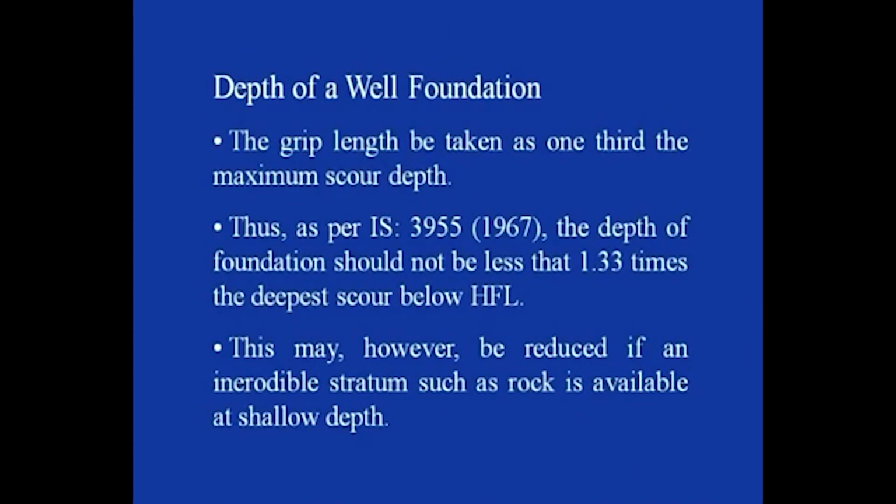Now the grip length of the well can be taken as 1/3 of the maximum scour depth. Therefore, as per IS code, the depth of foundation should not be less than 1.33 times the deepest scour below high flood level, that is HFL. So first, we need to obtain the depth of scour from Lacey's formula.